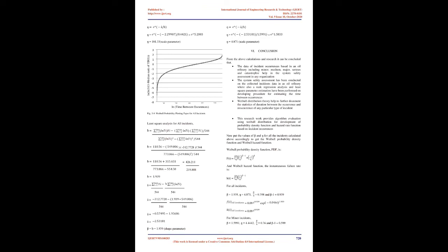Weibull analysis includes plotting the data and interpreting the plot, failure forecasting and prediction, evaluating corrective action plans, test substantiation for new designs with minimum cost, maintenance planning and cost-effective replacement strategies, spare parts forecasting, warranty analysis and support cost predictions, controlling production processes, calibration of complex design systems, i.e., CAD/CAM, finite element analysis, etc. Recommendations to management in response to service problems. Data problems and deficiencies include censored or suspended data, mixtures of failure modes, non-zero time origin, unknown ages for successful units, extremely small samples, as small as one failure, no failure data, early data missing.